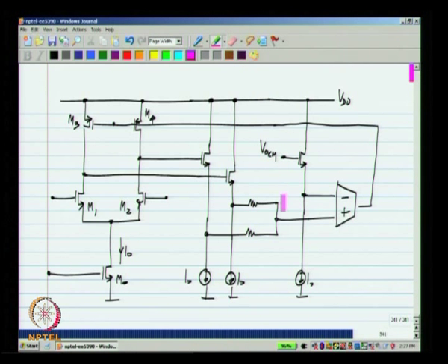Now, in this case, when the common mode feedback loop works properly, the common mode of these two voltages will be set to VOCM. MC11, MC12 and this MC11 prime are identical to each other. Okay. And we have this RCM and RCM here, and we usually also have to have these capacitors CCM to make sure that there is not too much delay in the common mode feedback loop. We also have to have Miller integrating capacitors.